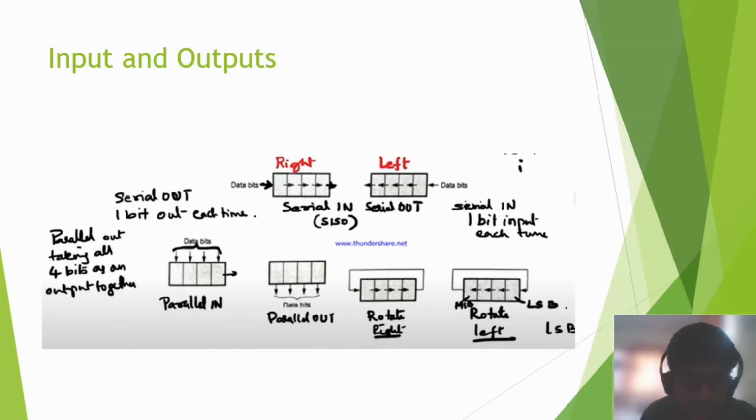And when it comes to the least significant bit, it again shifts to the most significant bit and this rotation continues. In rotate left, we provide the data in the least significant bit and the shift occurs from right to left to the most significant bit. When it reaches the most significant bit, the data bit goes again to the least significant bit and the rotation continues.